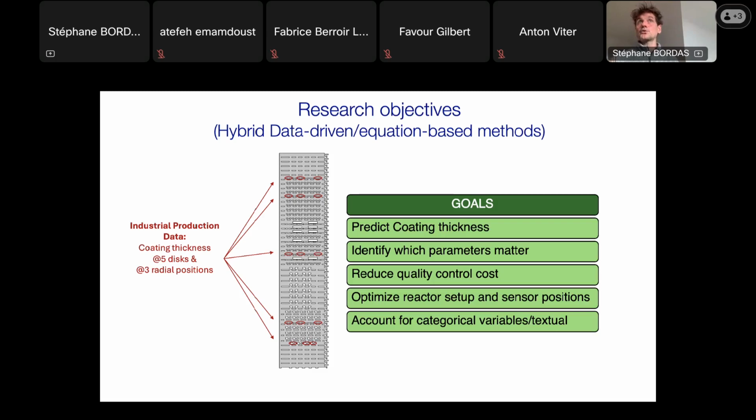So this is a pre-calculation. We measure the crack, we let the thing take off and land 5,000 times, then we measure the crack again, and we say, our model was not very right because I predicted a growth of 1 millimeter and it actually grew by 2, which is catastrophic.